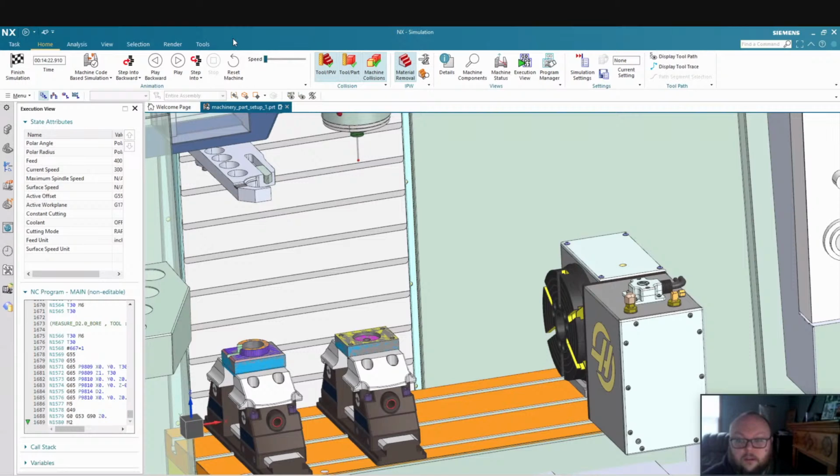You can do other things like have the machine alarm out if you're outside of tolerance. If you blow size on this bore and you're over the tolerance, you can have the machine alarm out so the operator is automatically or right away notified that something with this part's not in spec, and they can then look and see, can we rework it? Can we salvage this part, or is it going to be scrap?